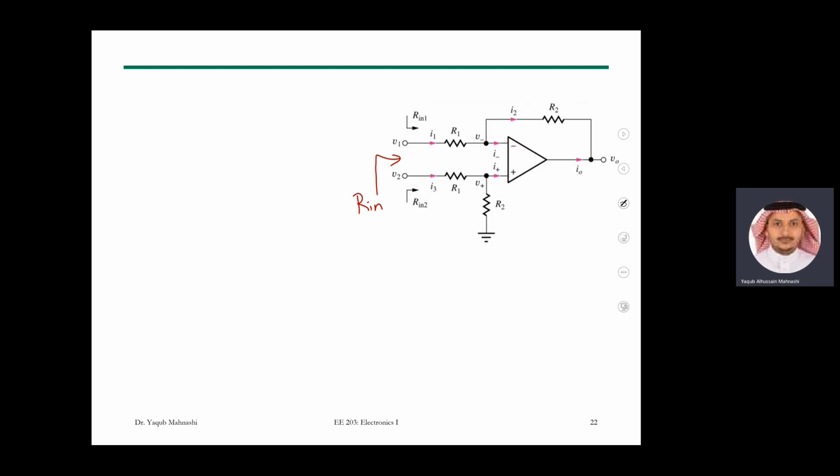So our input resistance needs to be the same as your Thevenin resistance, because this will result in the maximum power point. The maximum power point. If you draw it, guys, I expect you remember the power looks like this. The maximum power point is related to Rn equals the R Thevenin of your resistance. So it means your input resistance depends on the application. Are you looking for voltage, current, or power?